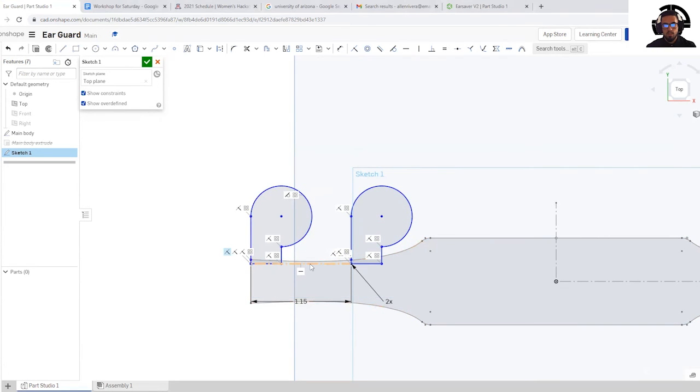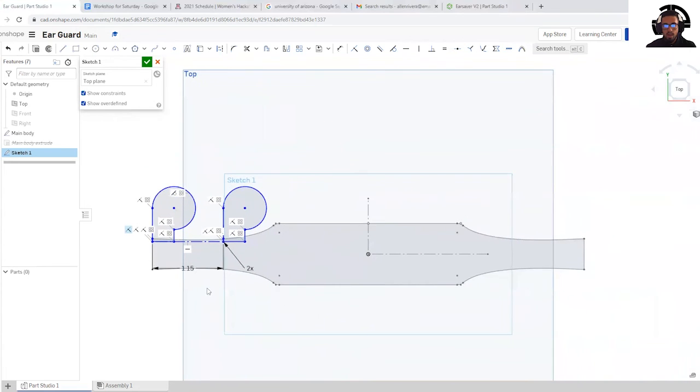Okay, and remember, this is a construction line, so you will not see this in the sketch. They will not be connected in any manner, and they will be their own part. But now I am only 1/4 of the way done, and I don't want to have to replicate that entire process of making these 2 onto the other side. So what do I do? Use that mirror function. It comes in super handy and it saves you a bunch of time.